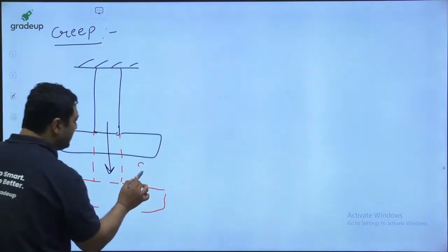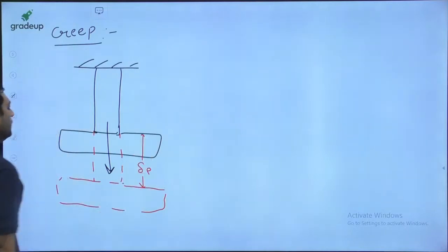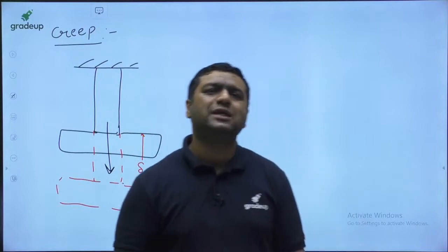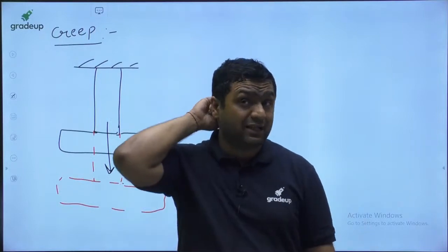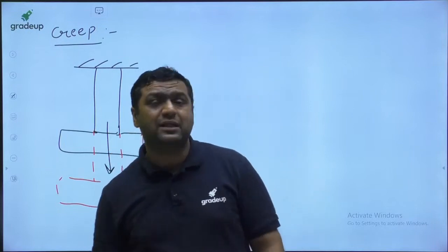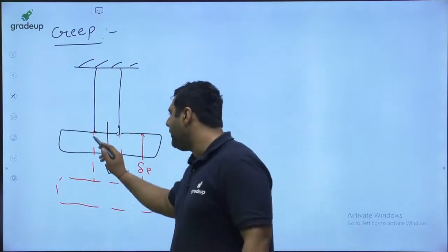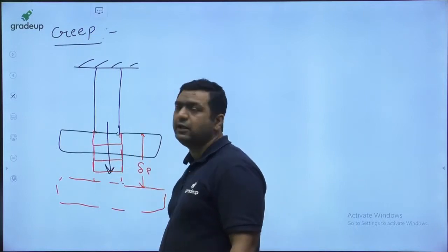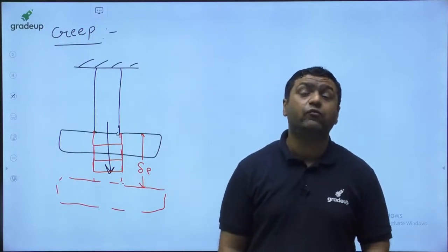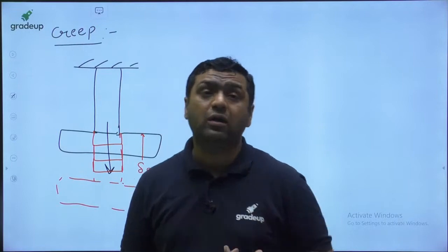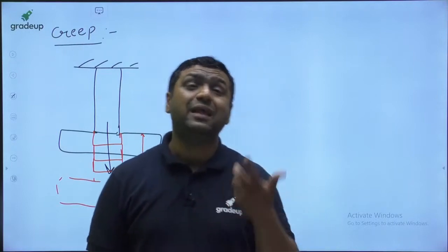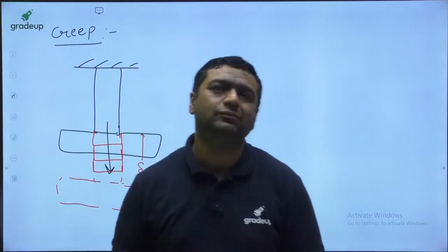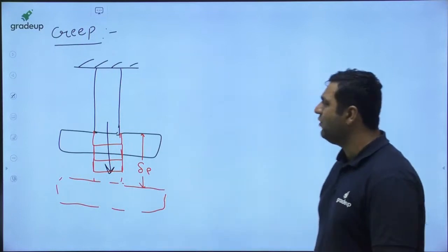So this is elastic deformation, for sure. When you apply the forces, it is elastic deformation. But my dear, when loads are applied for longer times, the elastic deformation starts getting converted into plastic. After some time, some part of the elastic deformation may get converted into plastic, and that phenomenon is said to be creep. This is more extensive when temperature effects are also there. At higher temperature, it affects more. Hope, my dear, you are getting it in a nice manner.